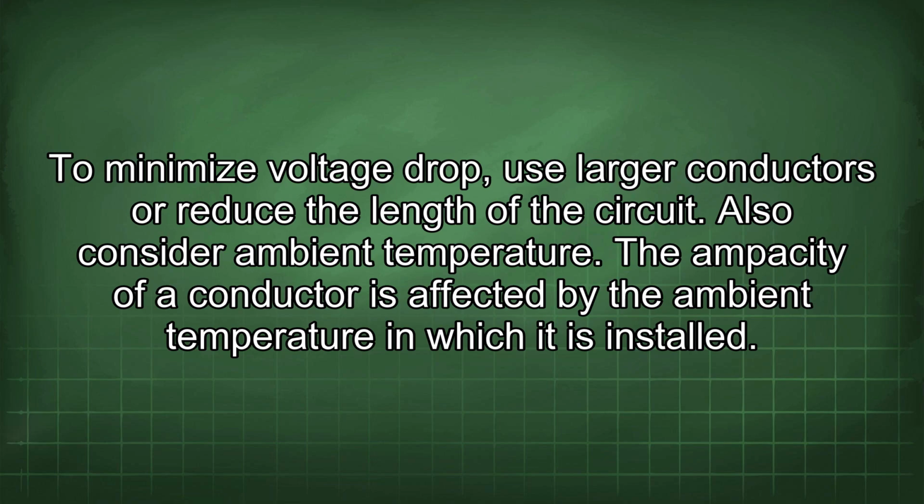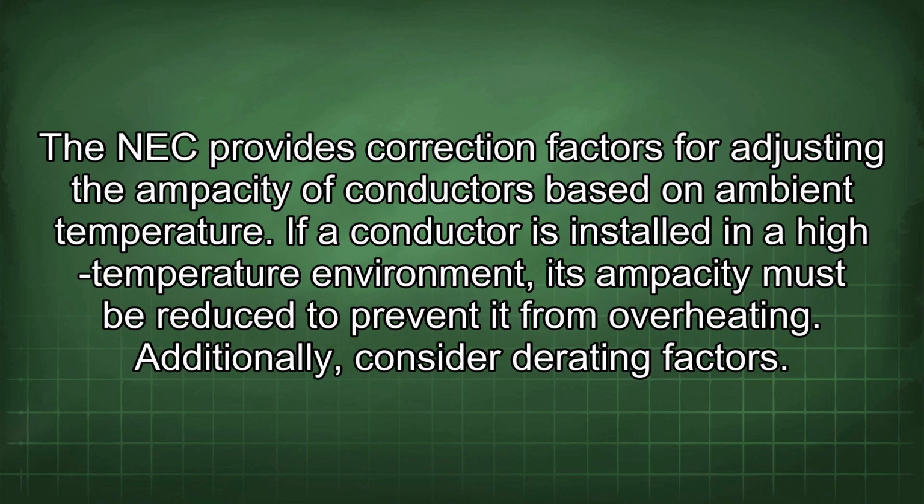Also consider ambient temperature. The ampacity of a conductor is affected by the ambient temperature in which it is installed. The NEC provides correction factors for adjusting the ampacity of conductors based on ambient temperature. If a conductor is installed in a high-temperature environment, its ampacity must be reduced to prevent it from overheating.